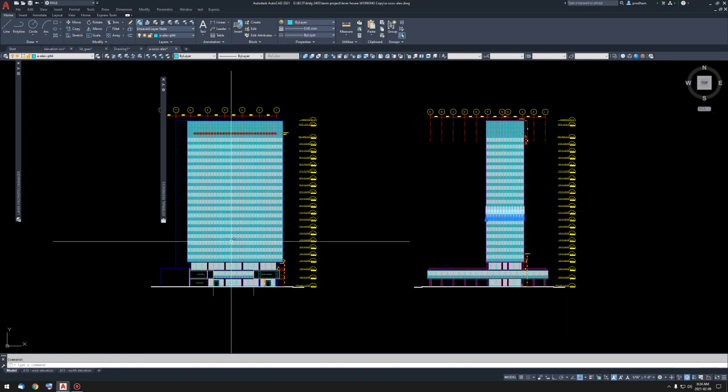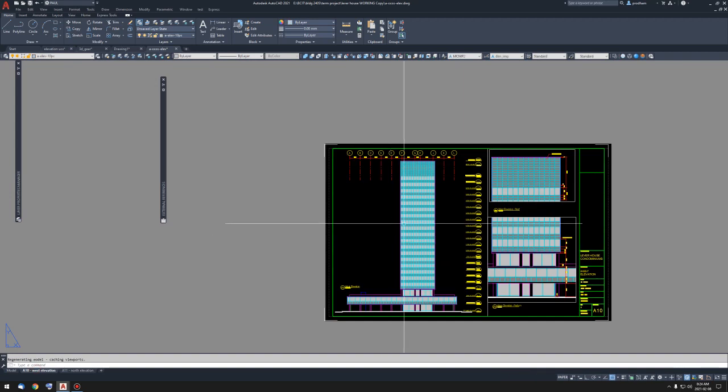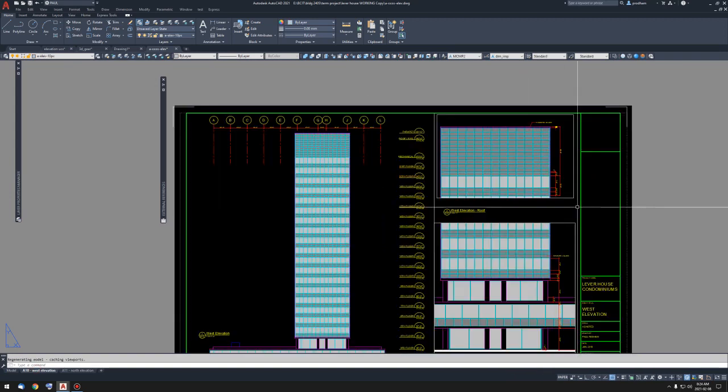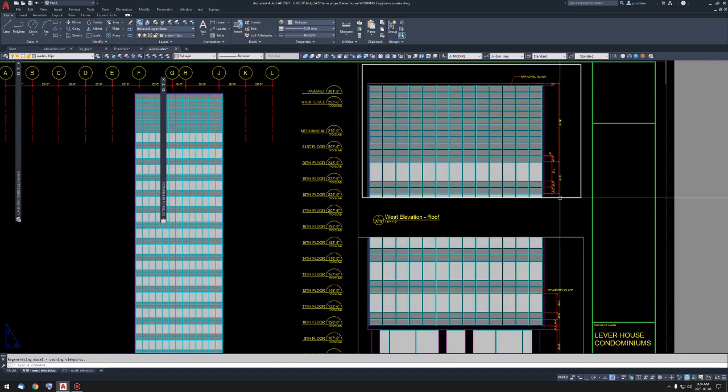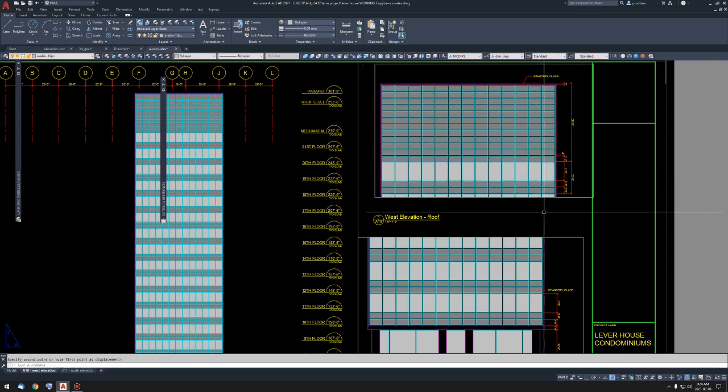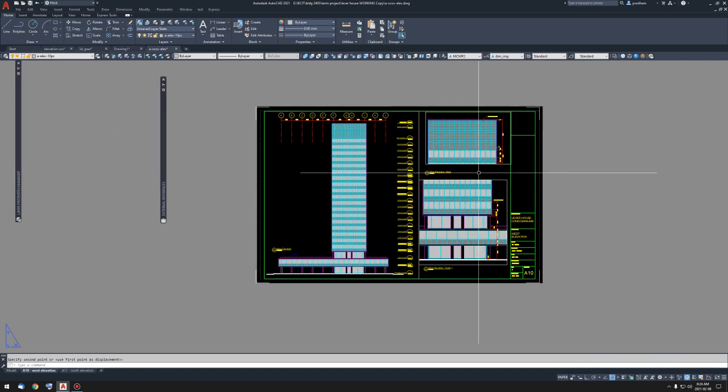Okay? When I go to Paperspace, you'll see that this is also a lot easier to work with. Setting up the viewports, again, shouldn't be anything different than what we've done before. Make sure these line up. Super critical. Every year, people end up doing this sort of thing, and that's downright embarrassing, to see a building go down and then angle like that. I mean, come on, you've got to be able to set that elevation up correctly. So make sure you do that.